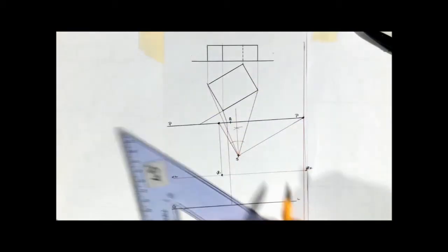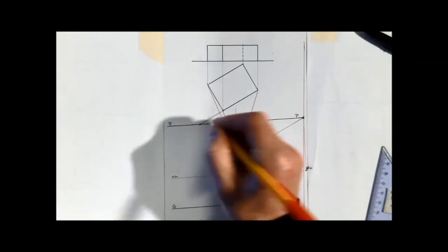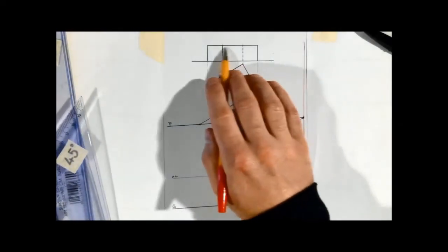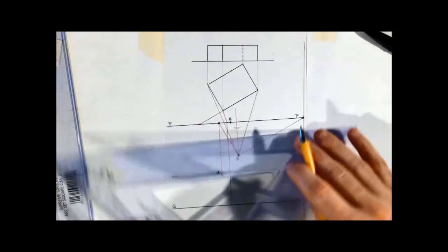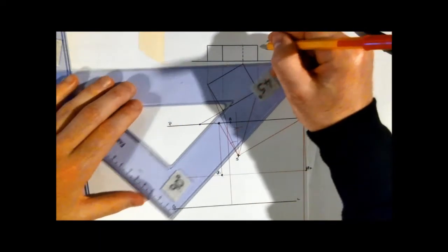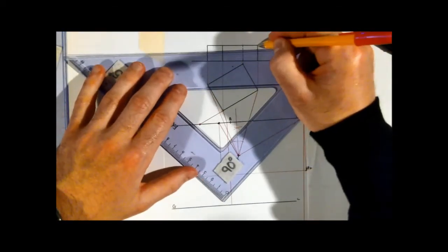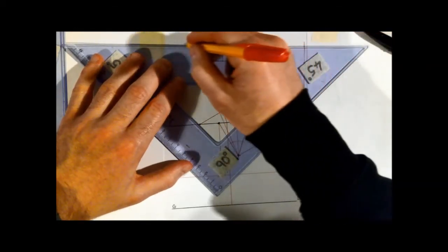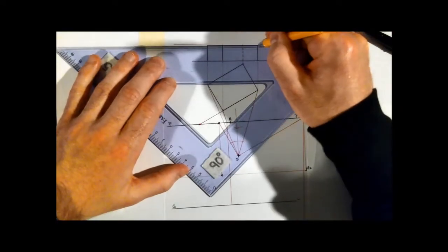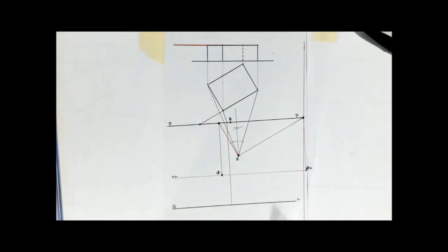And if we extend that down along here, it hits our picture plane right there. In reality, all I have actually done there is, if I actually did that up in elevation, watch, it was still at a height, as we know it's at a height of 15. So all I've done is, that line there, which is here, all I've done in elevation is I have brought that line out like that. Probably could have done a little bit more accurate there. Apologies. There we go. I could have just literally just brought it out like that.